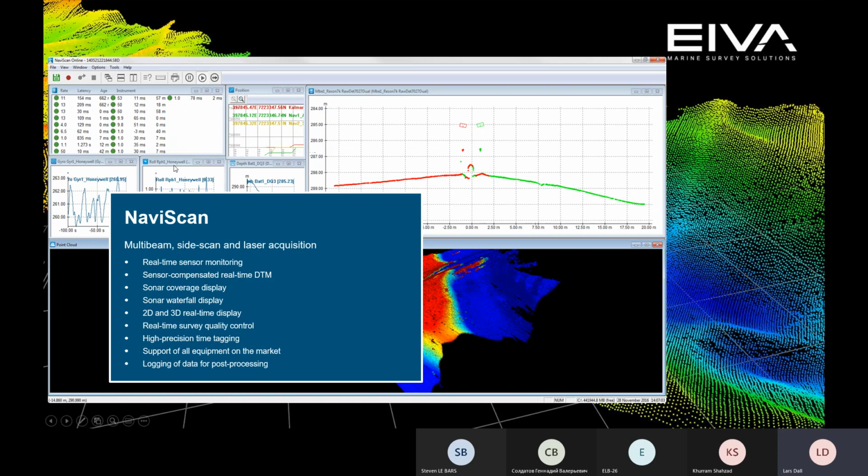Time series of gyro, roll, bathy. This is a position plot. This is a cross section of the multibeam data. You can see this is a dual head Reson 7K. The two heads are color coded. I did that. Naviscan doesn't do it automatically. You have to do it. So starboard side green, port side red, and then the overlap. Of course, this is the important part. Are they matching? And they are, as you can see here.